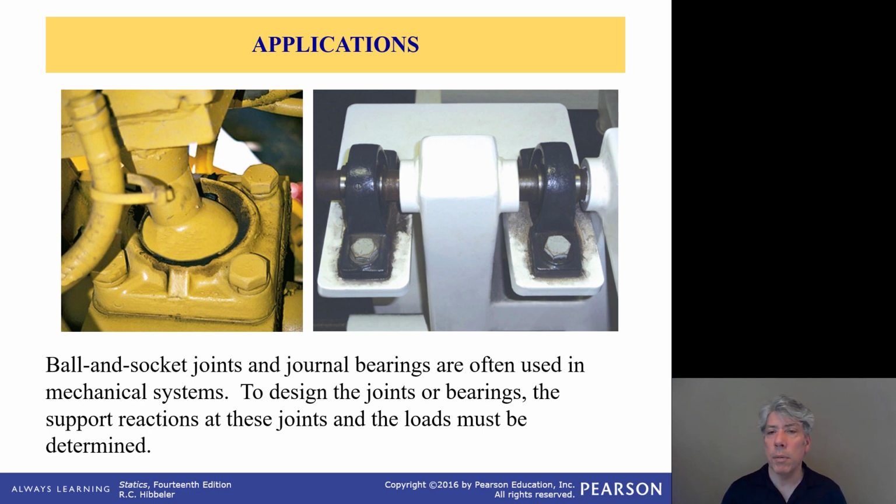This is probably a more valid assumption if you've actually worked with pillow block bearings, because a pillow block bearing has a bearing insert that typically has a hemispherical feature such that the bearing itself can rotate inside of the bearing housing, inside of the block, so to speak. That allows misalignment. So the shaft can run through the bearing and not necessarily be perfectly perpendicular to the body of the bearing's housing. They're called self-aligning, not so much because the bearings themselves are self-aligning, but because the interface between the packaged bearing and the housing is self-aligning.